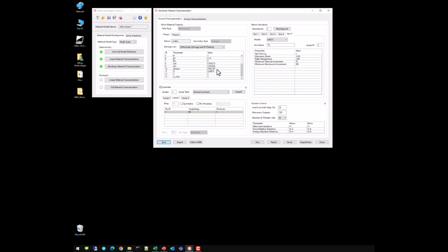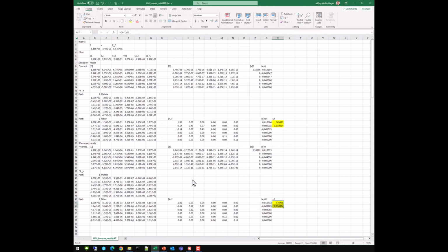Okay, let's work on the matrix brittle behavior next. So we'll go back to our sheet here, and matrix brittle is in tension. So we're just going to start another column here for the stresses of the 90-degree specimen, which are 0, because I don't have a stress in the one direction, but 7,086 PSI in the two direction.